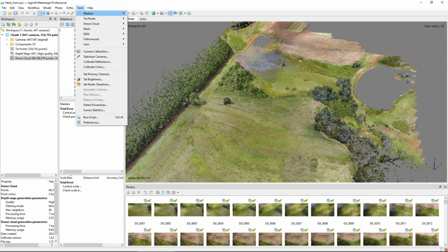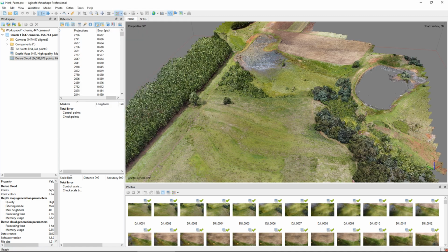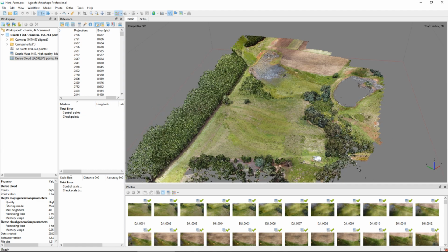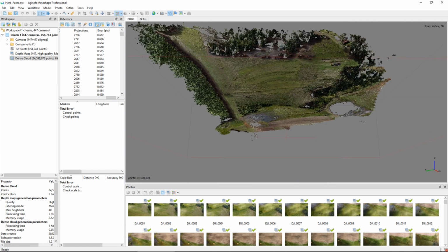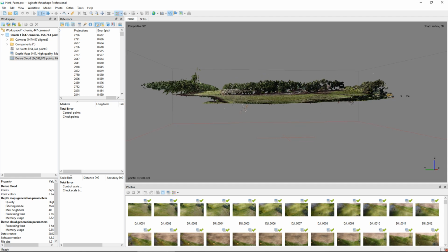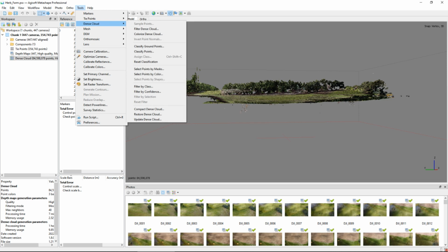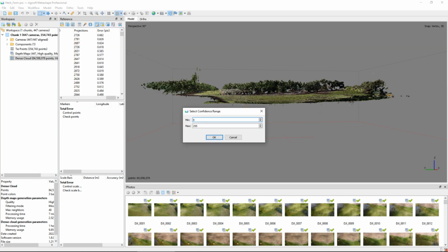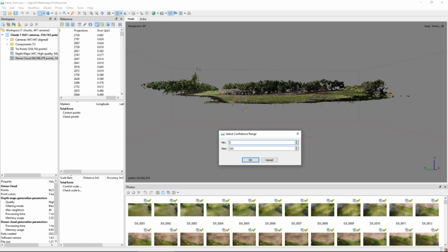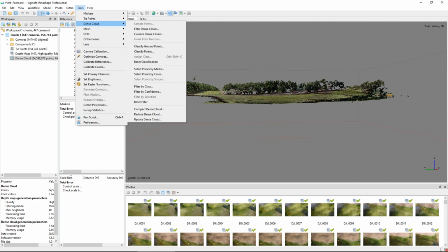More expensive and higher quality cameras tend to have fewer erroneous points. The quality of your capture could also play a role here, so it's not just a price or quality of camera scenario. Take this time to observe your point cloud very carefully and filter it, going through each step nice and slowly, making sure that you choose the optimal setting. You don't want to have to spend a few hours recreating the dense cloud again.